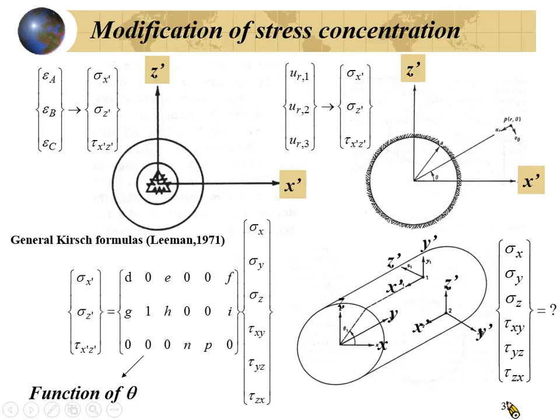At any single point, the stress here will be determined or influenced by the global stress tensor. So right now you can imagine you have a tunnel, and you will have a three-dimensional boundary stress. Before you had only two-dimensional boundary stress, right? If I have a tunnel and a boundary stress, sigma x, sigma y, for example, then you can calculate the stress at any single point.